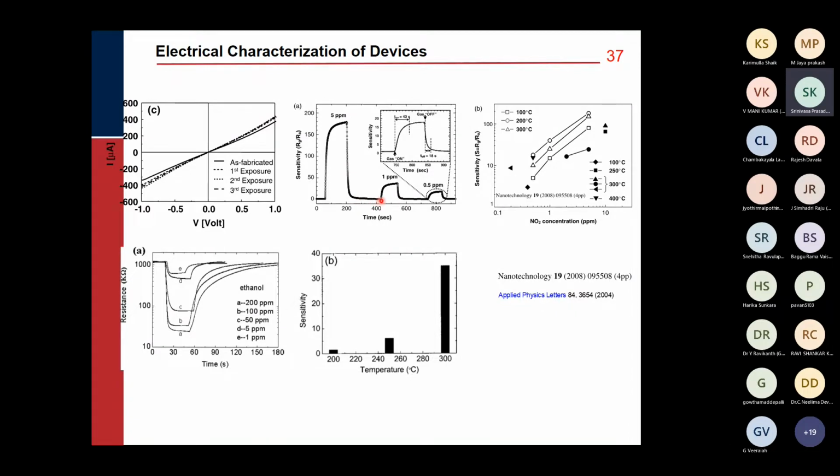So it is again reaching this bottom level. Now you pass the gas again, but at a lower concentration than this one. So now it is 1 ppm. Here also, as soon as the gas enters, it will increase, and then once it reaches saturation, you stop it, then it will come down, and you can subsequently do it at different conditions. That way you can get an idea of how the sensitivity of this system works.